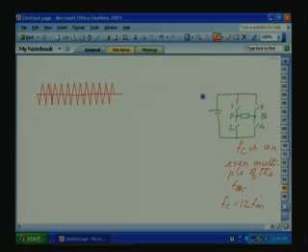Now, let us draw it also for the A phase and B phase. The fundamental should be in opposite phase, so we will use 180 degree opposite sine waves for modulating the two legs. Let us take a different color.